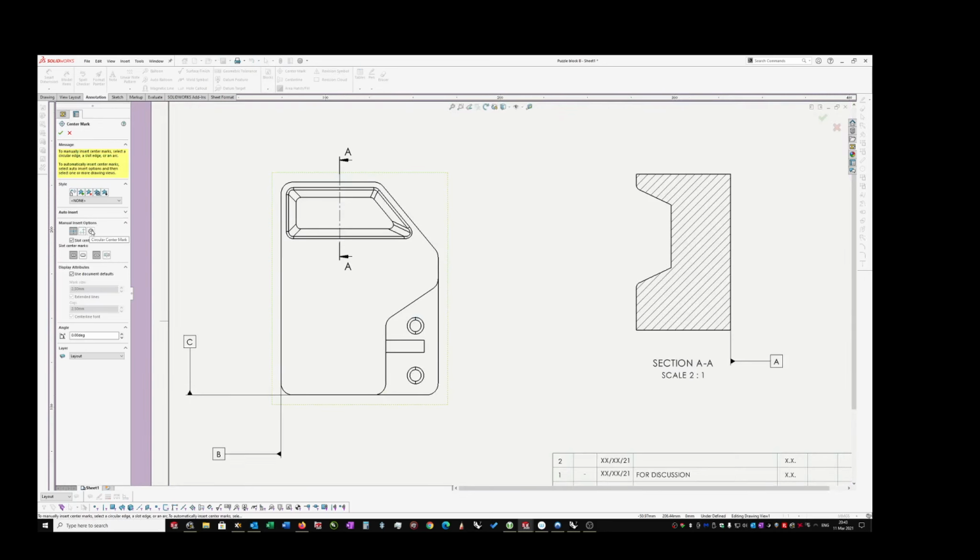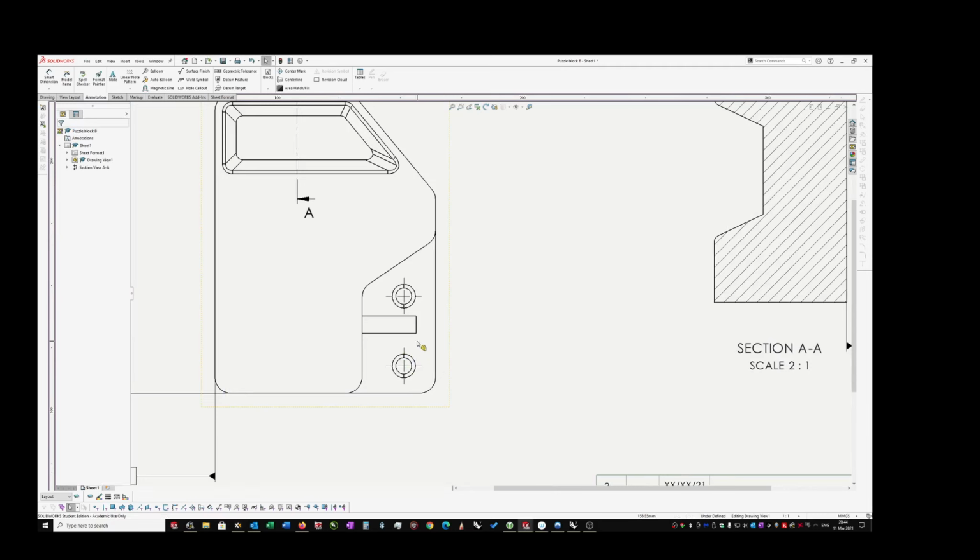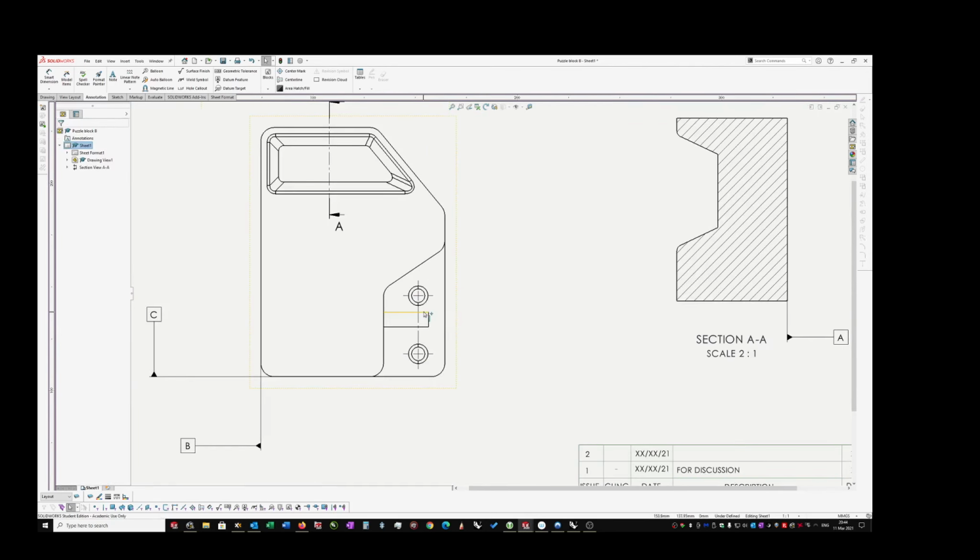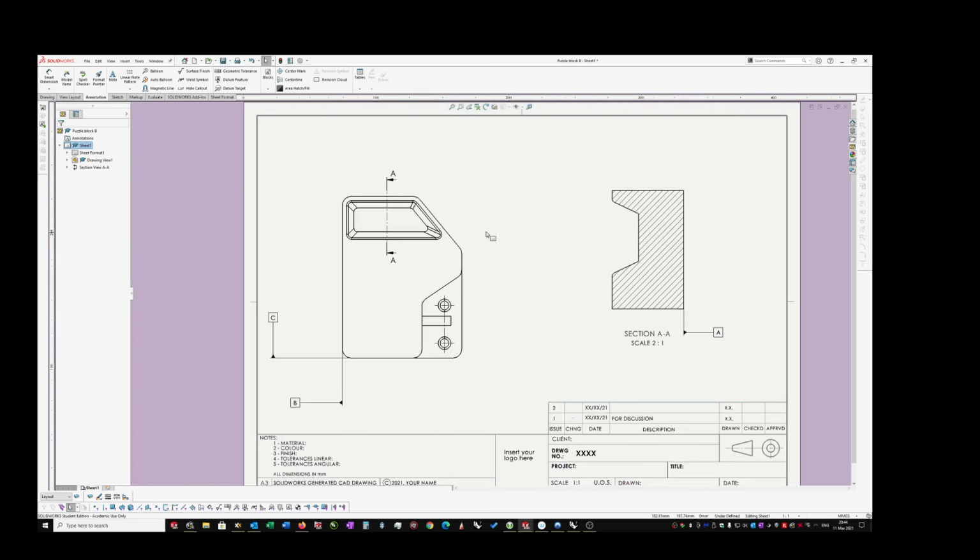And I can just click on this circular center mark and click on, let's see if this works. There you go, beautiful. Just click on these two circles. You're going to need those center lines, and in fact you want to join, I don't know if this is possible, you want to join this center line to that one, which you can. Okay, so now it's clear that that center line and that circle there, that sort of peg and that peg share the same center line.